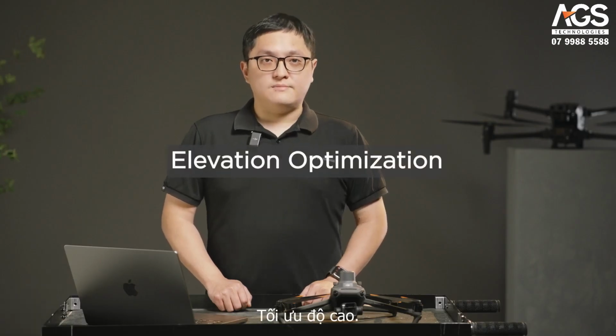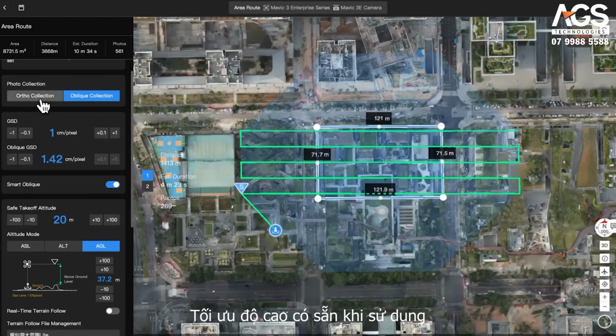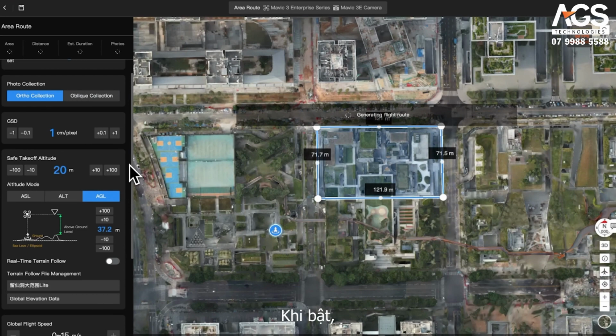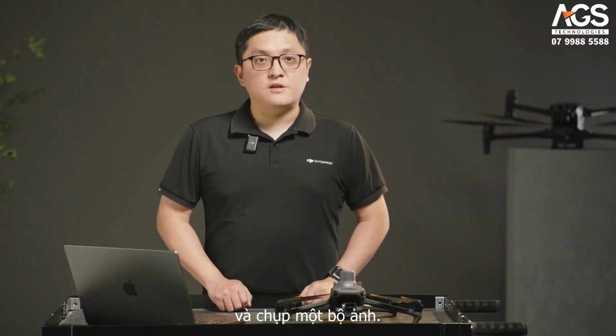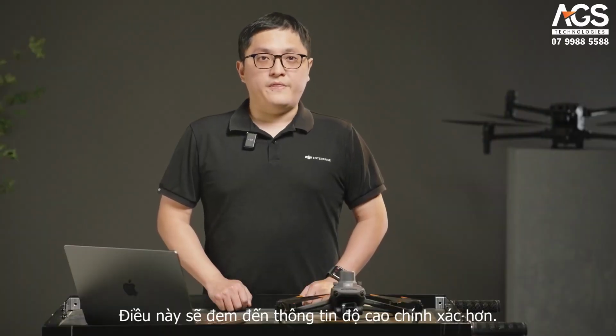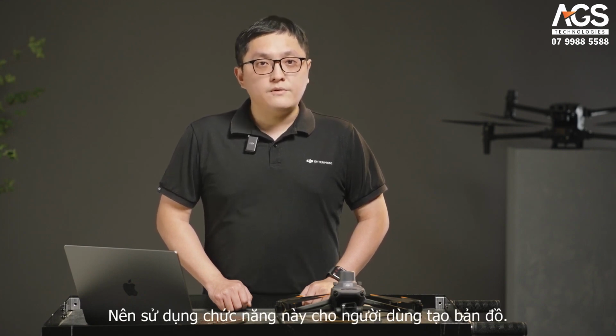Elevation optimization. Elevation optimization is available when using ortho collection. When turned on, the aircraft will fly towards the center after the mission is finished and capture a set of photos. This will result in more accurate altitude information. It is recommended to enable for mapping users.